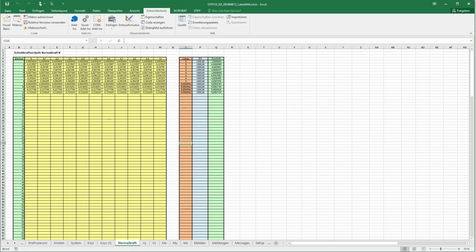Here the table about the normal forces for each of the elements 1 to 12 in 1/10 steps distribution, the length, the longitudinal stiffness. Eventually, interesting for the force density and form finding technology, the unstrained reference length, the cutting pattern.